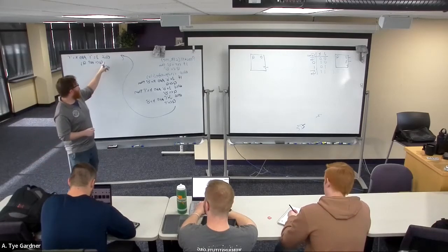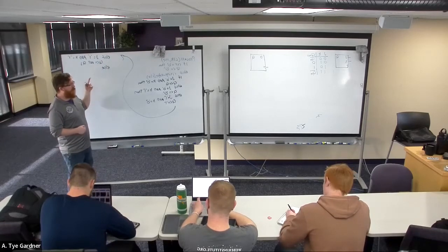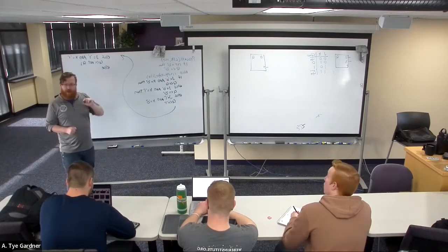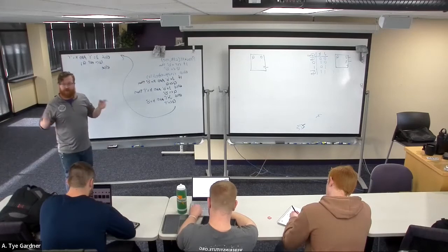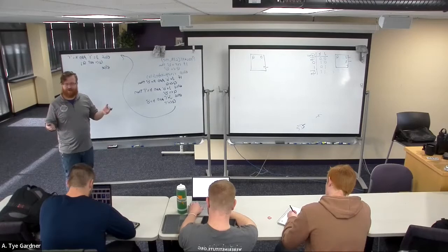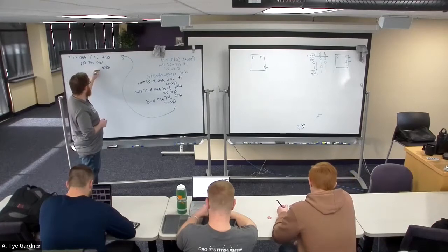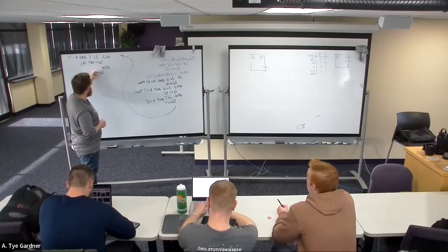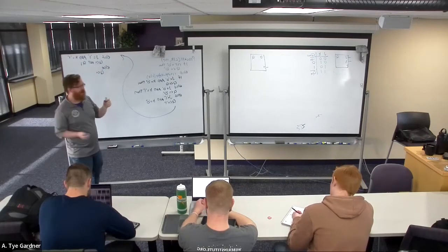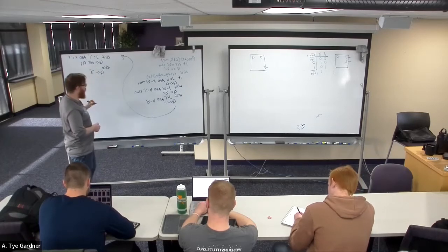Because right now, if I were to treat this as else, Q equals not Q, well, that would say that in any other condition besides the first 3, we're just going to invert Q. But if my J is undefined, if I didn't connect it, I don't want to invert Q, right? I want to let myself know that I just connected something wrong. So for the sake of you guys, you're going to say Q is assigned to, and I don't really care which one you do. I recommend X's because they look bad. I'm sorry. And it has to be a capital X.